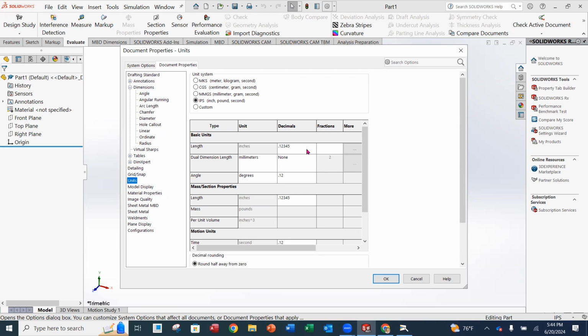You can set yours to 4 or 6 or 13 or whatever you want it to be, but I like to have 5 because when I'm converting fractional inches, when we get down into the 32nds and the 64ths, there's 5 decimal places there. And I want to be able to enter each one of those. Okay. So make sure that it's for each one of the links there. And everything else can remain the same. And we're simply going to hit OK.